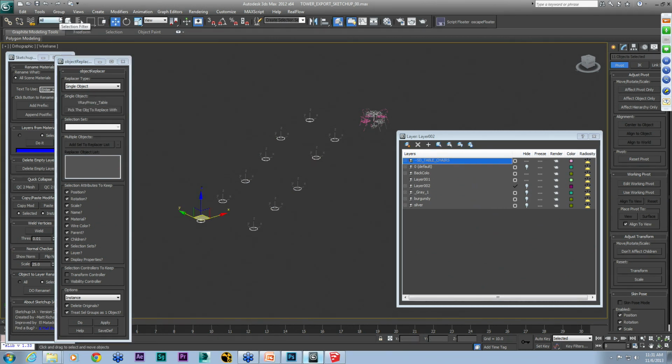Then we can take this, select our objects, the object we want to replace with. If you select just the object itself, you'll replace it with just the table. But if you open the group really quickly and you select the group, let's close that back down. You can actually replace all these objects if you use this option here, treat selected groups as one object, with a group.